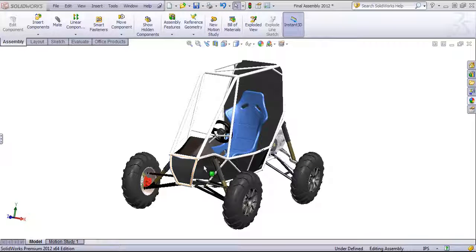Also, surface modeling in an example like this is great for setting up a rendering. These panels are all just simple surfaces created using either filled surfaces or boundary surfaces, and they're pretty much just made so I could create a PhotoView rendering of this entire assembly.